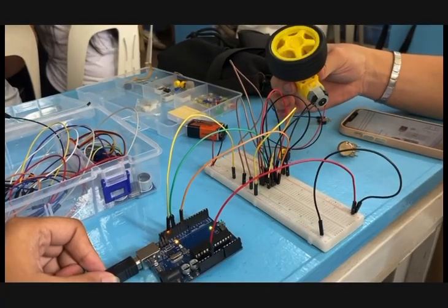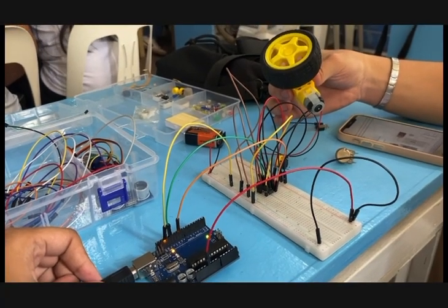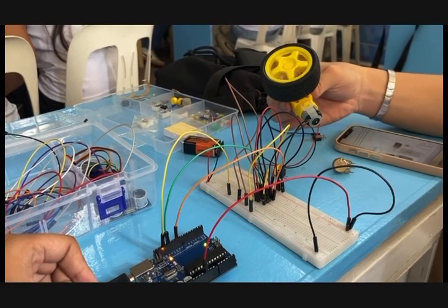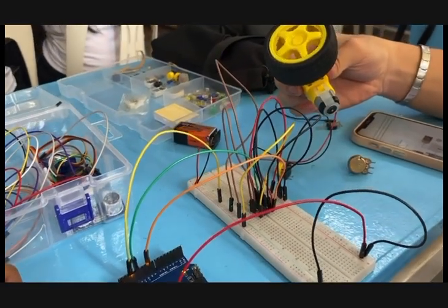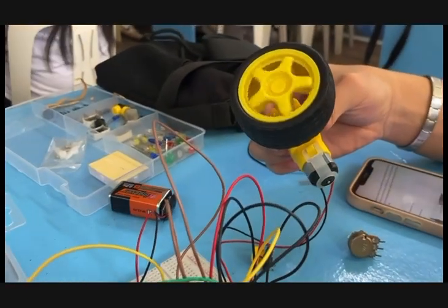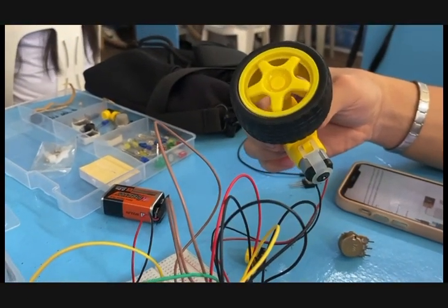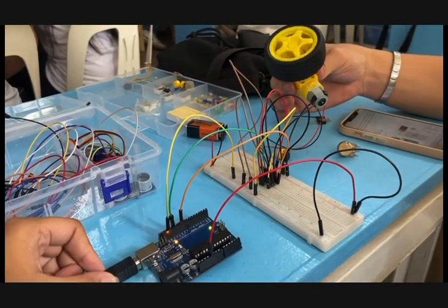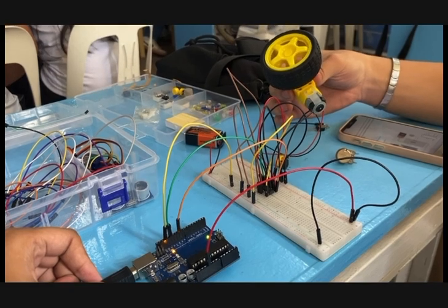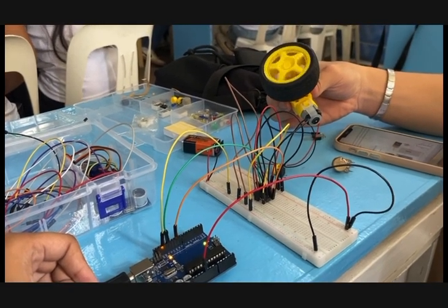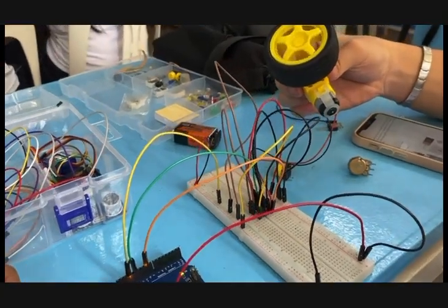We controlled the DC motor speed using PWM through the L293D motor driver and Arduino. The motor gradually sped up and slowed down, showing how digital signals can mimic analog control. We faced uneven speed changes at first, which we fixed by adjusting delay timing. This can be applied in fan speed controllers, electric toys, and motor-driven automation systems.